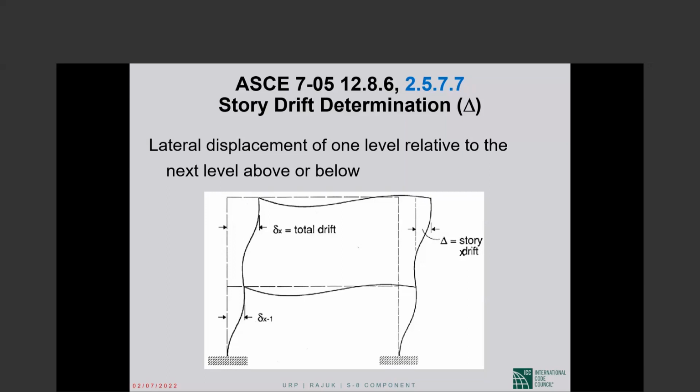This is beyond life safety. The other place where we go beyond strict life safety is when we include an importance factor larger than one in design. That also takes us in the same direction of damage control and continued functioning of the structure during and following an earthquake.